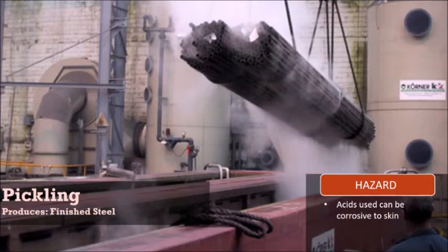The pickling process is used to remove a thin layer of metal from the stainless steel part. This is different from the descaling process, which removes visibly thick oxide scale from the stainless steel part. Our pickling solutions for stainless steel are mixtures of nitric acid and hydrofluoric acid. Corrosion on the part can occur if the process is not done by a pickling specialist. After the process is finished, it produces the finished steel. The hazards of this process are the acids that can be corrosive to the skin.